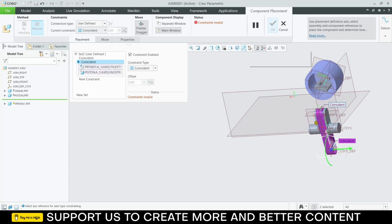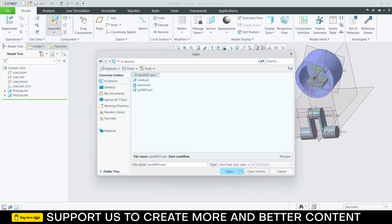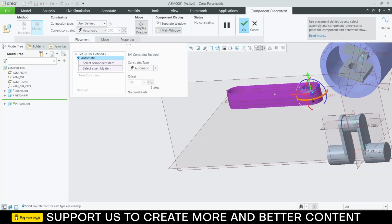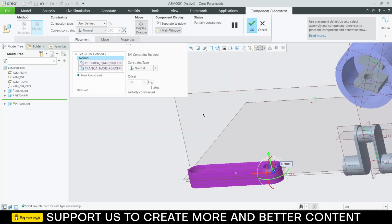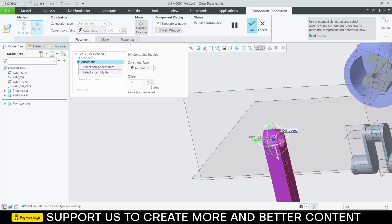Okay, here's the thing: I have made a mistake here. Click on close first, yes. So basically, when you try to make mates, whenever you create a new mate, you have to add new constraints. So watch carefully what mistake I made. I imported the part. So if I select this and this one, click on coincident. Now after I'm happy with it, click on new constraints. So this was my mistake. I didn't do that.